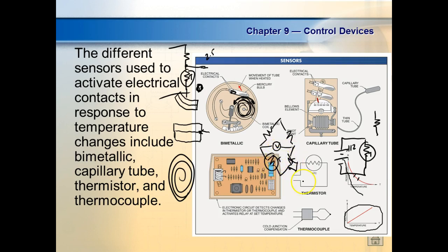So I would take my thermistor and put it into a glass of ice water, right? You understand? And then I'd adjust that resistor until my meter measures 0. The advantage of a Wheatstone bridge is it allows us to set a reference point for a sensor that varies its resistance. It allows us to set our reference point, right?